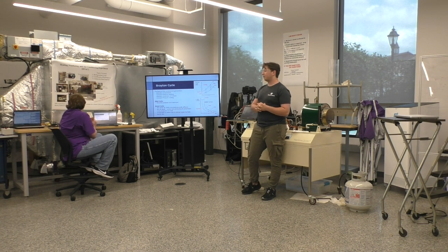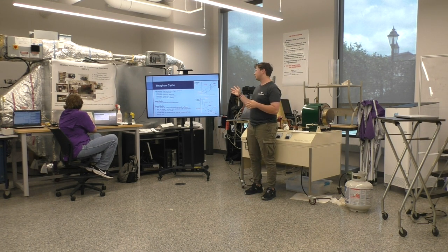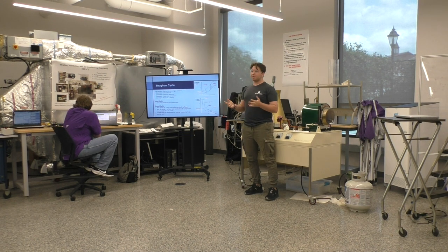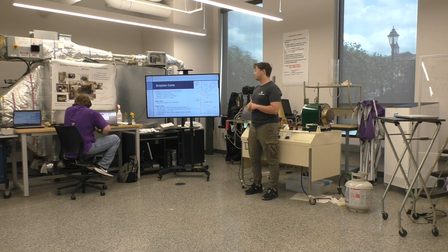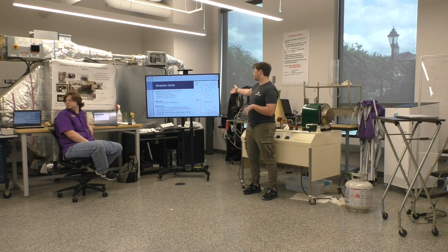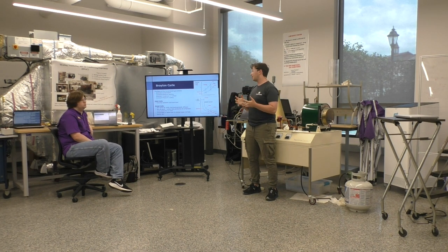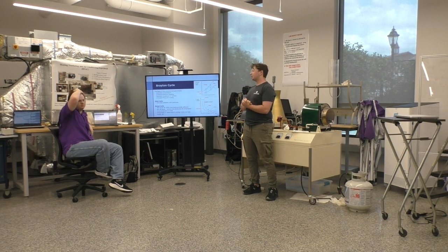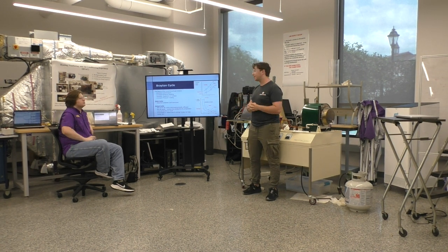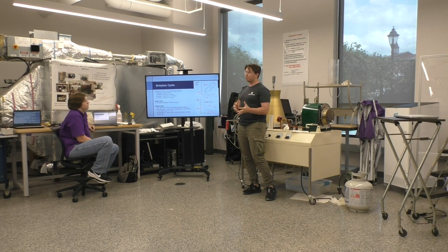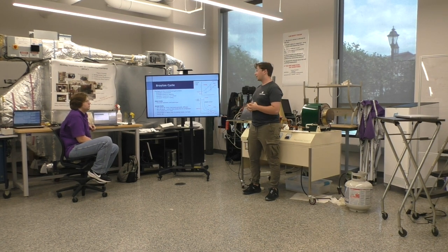So a little background, the Brayton cycle is the basis for this experiment. And of course, we know the difference between an ideal and an actual cycle. So assuming an ideal cycle, which is what's pictured here on the left, there are basically four steps. There's an adiabatic compression, there's a constant pressure heating or addition of heat, adiabatic expansion, which is going to be in the turbine, and then the constant pressure relief of heat, cooling.